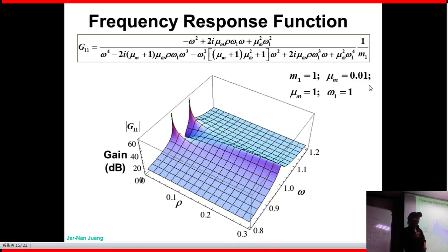That makes sense, because, of course, I want my tuned mass damper to oscillate with my system, so that the energy will be able to transfer from my system to my tuned mass system. And then that part will be able to take out the energy transferred from the system, right? That makes sense. That's why we have omega like that. Then this shows you, except this all fixed. I say, okay, now I have this is my damping ratio.